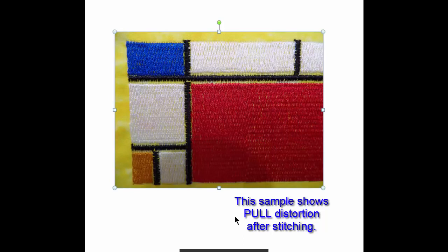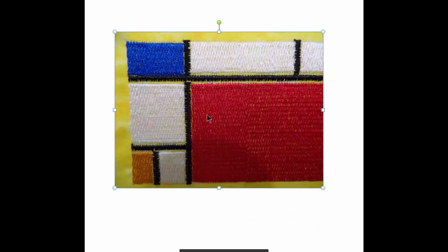I have lots of gaps between all of those rectangles in the columnar work of the black. How to fix it? The gaps were about 1/16, 1/8 of an inch, so I went in and changed each of the rectangles to a pull compensation of 0.3 millimeter. All rectangles were adjusted individually.